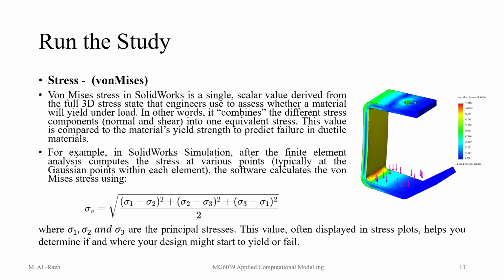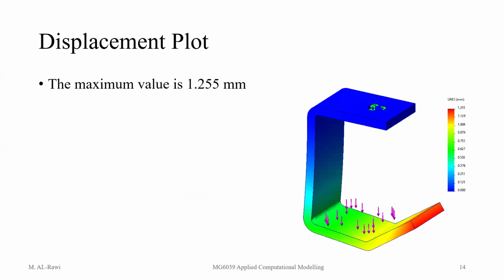All right, so what do we do now? Check the other one, the displacement. Double click on displacement in the results. You see that the result will show you displacement in millimeters. The maximum displacement for this design for me is 1.25 millimeters. And you can check the other ones, there's displacement and there's stress or strain. You can click on any one of them just to explore.